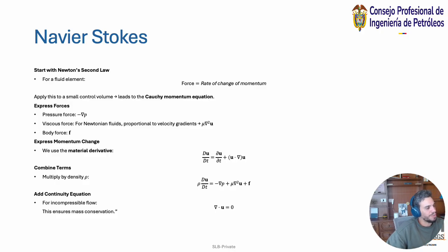And then finally, you can combine them and set them equal to the continuity equation for an incompressible flow. Here we're just sticking to the laws of the conservation of mass, right? So you see this equation just about everywhere in multiple industries, whether you're designing aircraft or cars, predicting weather and ocean currents, or trying to model flow. Even in medicine, with non-Newtonian fluids, like our blood is non-Newtonian.